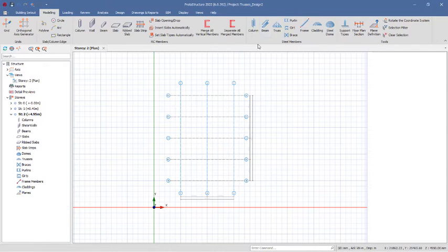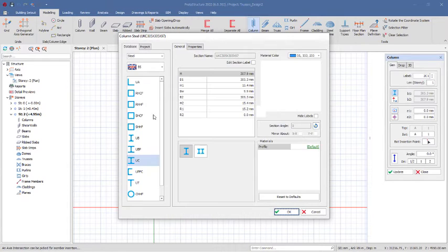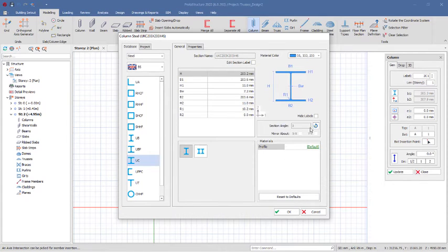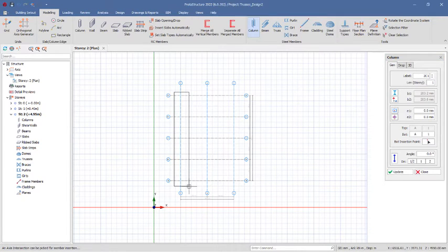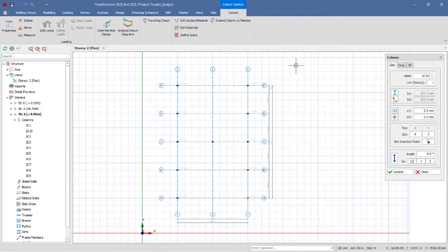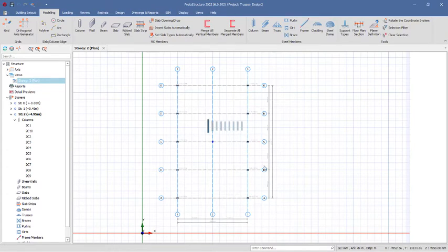At story 2, we're placing our stanchions. So click on the steel columns. We change these sections so we can get smaller sections of the universal columns. So we select there. Okay, so we are considering British. This is 303 by 303. It's quite bigger, so let's go by 203 by 203 by 46, because it's a small structure. So we add that up. We are going to be rotating in this direction. Click on OK. So we have it placed on these provisions, just like this, and the same thing here. Alright. So having done this successfully, we click on the OK option and then we will go to the 3D to see what we have done so far.